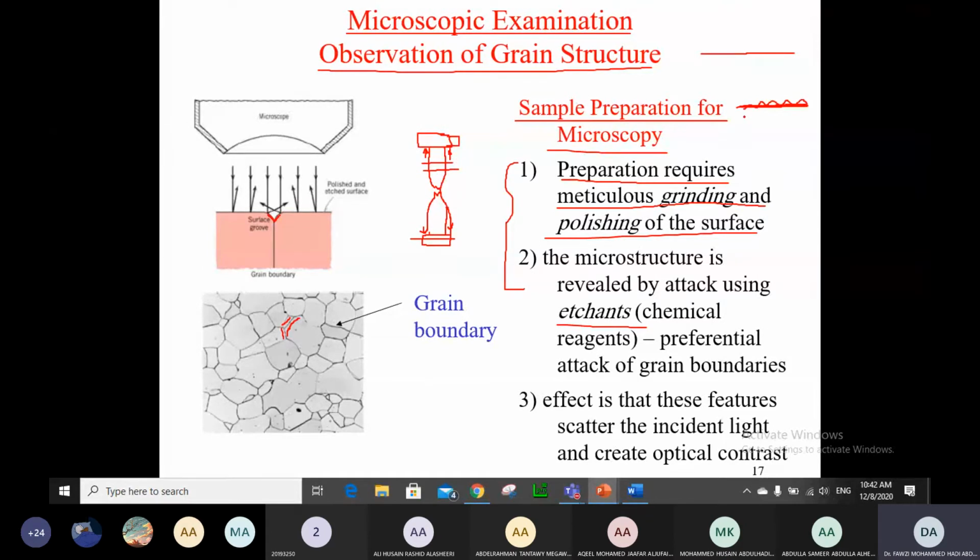Why do we make the surface very straight? Well, if the surface is not very straight and it has all that, then if you put an acid there, it would not really show the contrast between the straight surface and the parts which are eaten by the acid. There will not be any contrast there. There won't be a difference between them. That's why we make sure we have a very straight surface first. Then this will be successful. When you add the agent, it will make these grooves, which will show. If these were there with the grooves, you wouldn't be able to recognize the grain boundaries there.